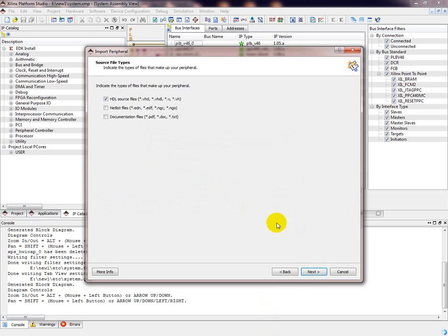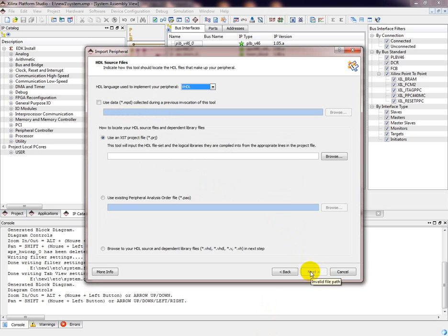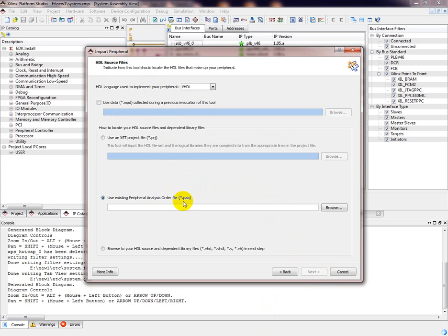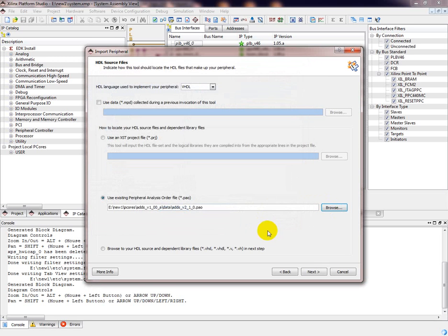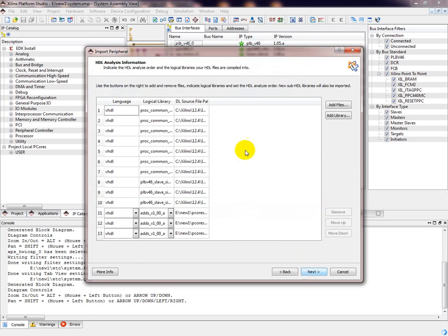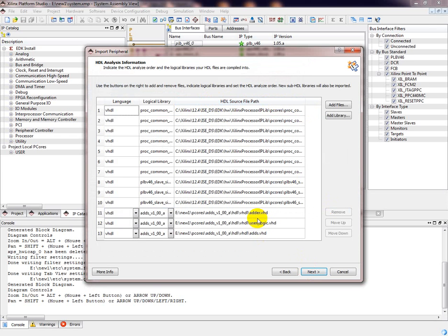Yeah. So next thing is now in this file, we are supposed to specify the POW file. We have made changes to the POW file. So here we have to give the path of the POW file, because in this file the hierarchy is there. If the hierarchy is correct, it will be visible here. If the hierarchy is wrong in your file, it should be addx, then user logic, then adder. Otherwise, this will be shuffled and it will say error. It looks for this order. So you have to paste correctly in the POW file, right?